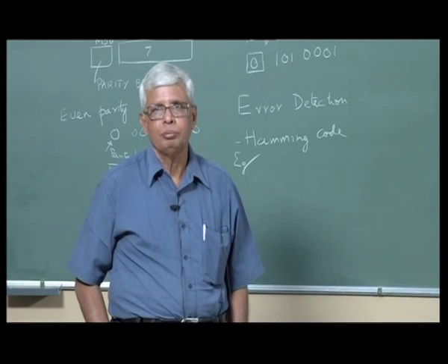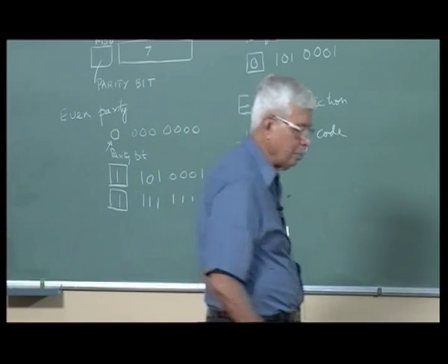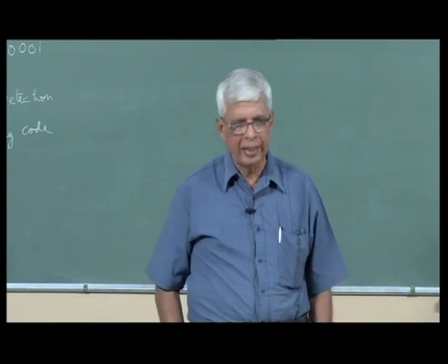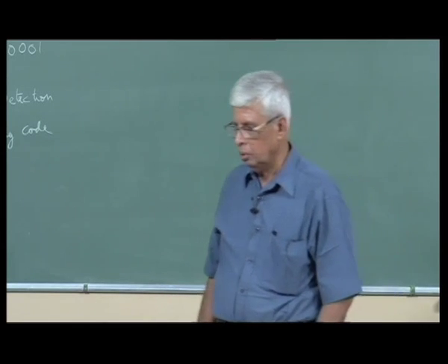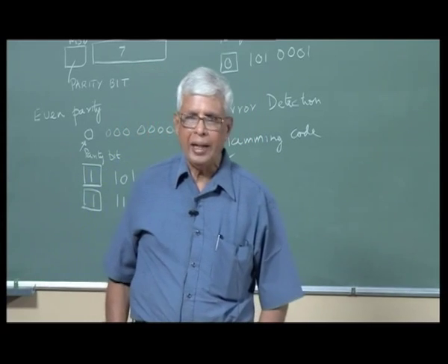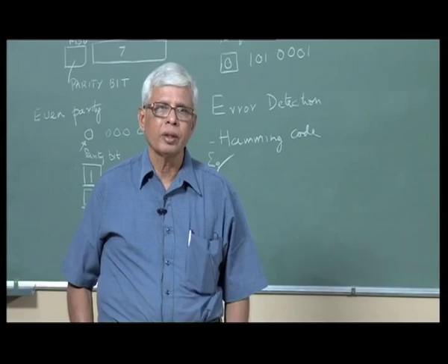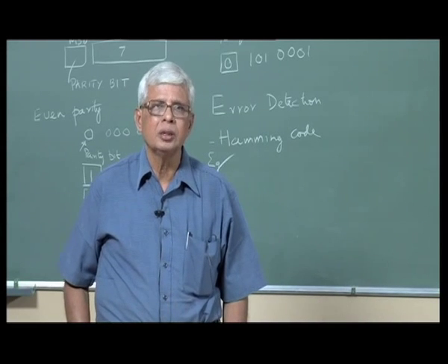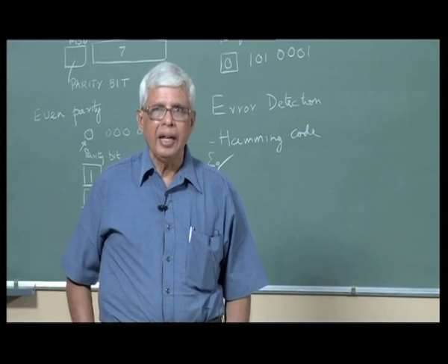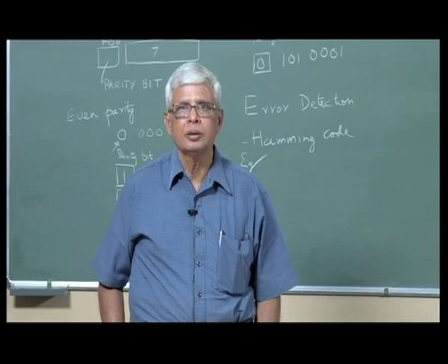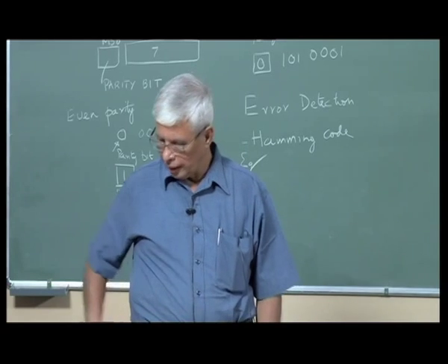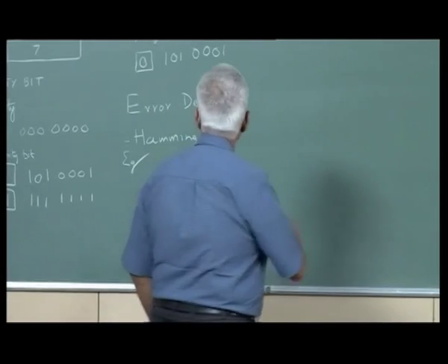What is an overflow? See, you add numbers in the arithmetic unit, in what is known as the accumulator. I hope you all have a microprocessor background, or you will learn soon. You add numbers in hardware called the accumulator. The accumulator has 2 inputs and 1 output. The two inputs add. So supposing we have 8-bit data in 2's complement, 1 is the sign bit and 7 are magnitude bits. So with 8-bit 2's complement, I will talk about overflow now.